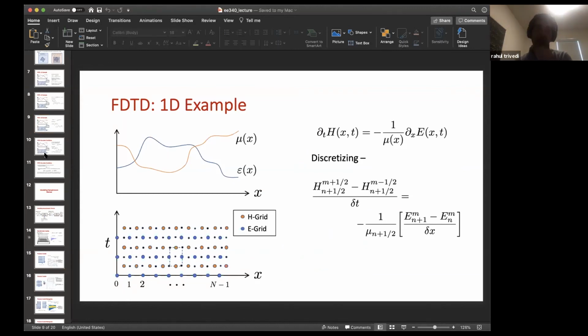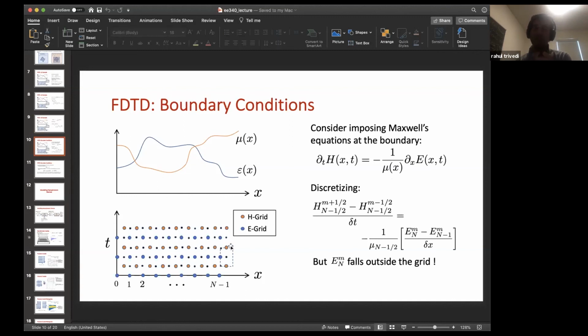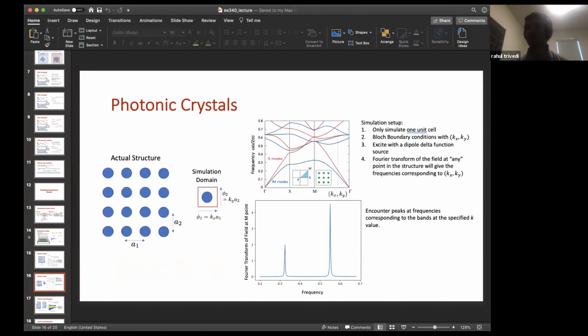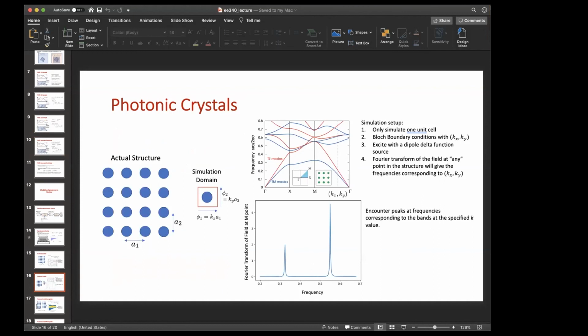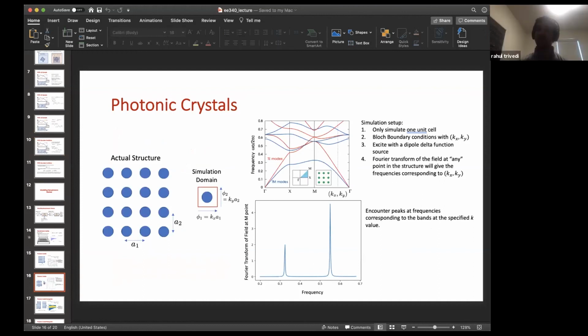And the reason why it needs to be complex is because when you impose your boundary condition on this cell, you introduce a complex number exponential i phi in your simulation. So you end up getting complex update equations. So even if you start with real fields, they'll become complex at some point. And you can do this Fourier transform on complex fields. And again, even for these simulations, you can use the harmonic inversion package. So you can fit a bunch of, in this case, just sinusoids and not really decaying exponentials, on your signal. So you don't need to simulate for an indefinitely long period of time. Okay, does this make sense?